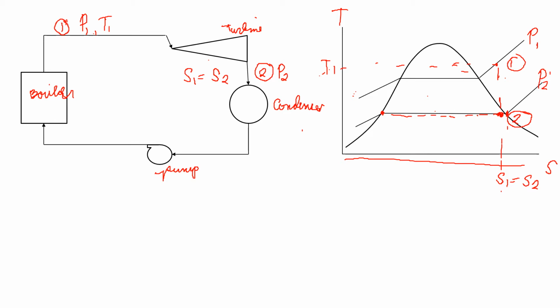Now the main purpose of your turbine is to produce work. Here, this line here, it produces work. And as it goes from the high pressure to the lowest pressure, we see this enthalpy line. There are differences of that H. This is your H1 and your H2.